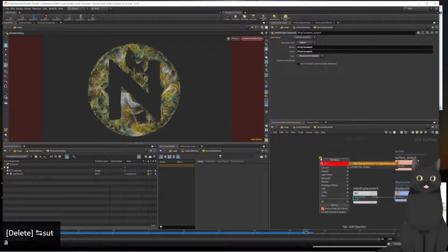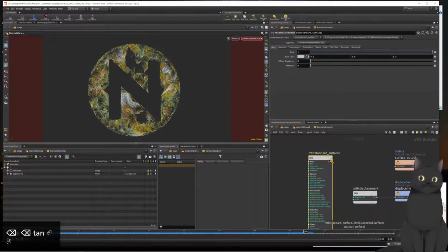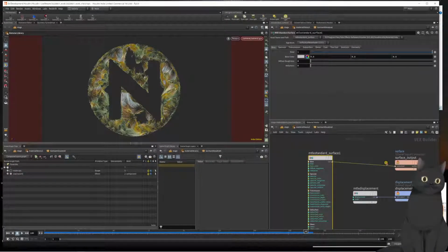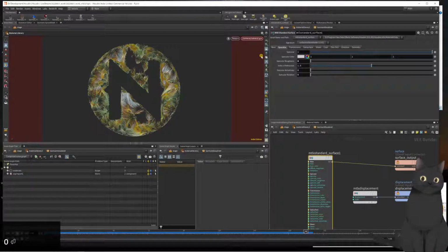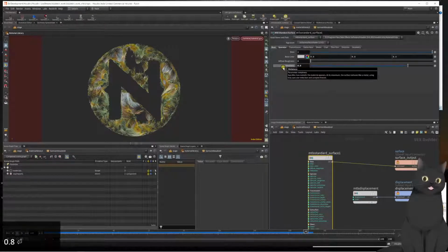Let's wire in the out to the global output, and in here I want to go for a more metal-like look. So under the specular, let's decrease roughness, so we really have like shiny reflective metal. And under the base here, let's increase the metalness, in my case to 0.8, again trial and error when preparing the setup here. And now let's load up the color of those streamlines and use them for shading.